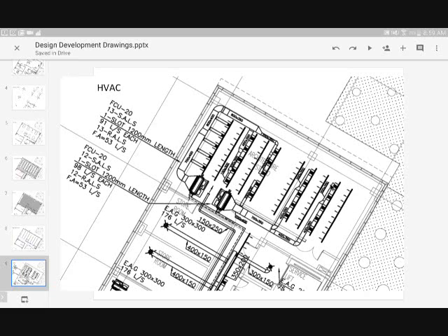Okay, no, 200 by 350. So it's a small duct, 20 by 35 centimeters, that provides air to the last unit. So we bring air and we take the air back to the unit. So it uses the same air and provides new fresh air with it, about maybe 20% fresh air, and uses the air again, so its temperature is already cool.